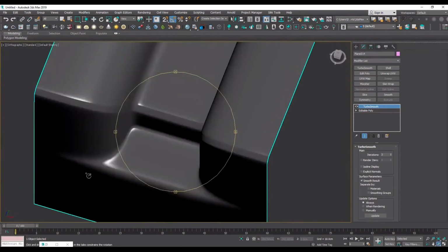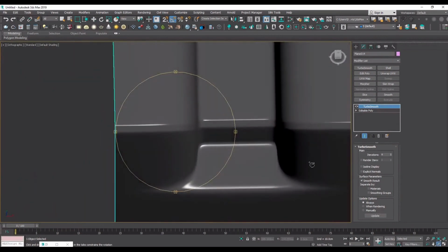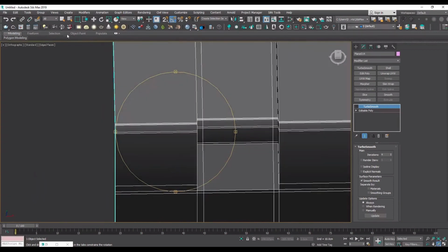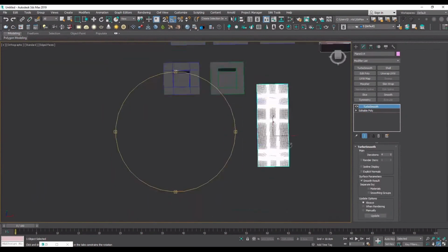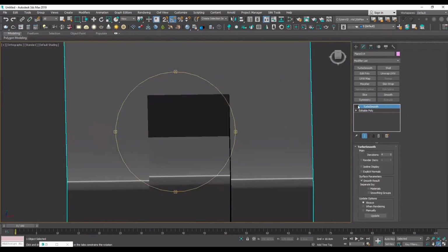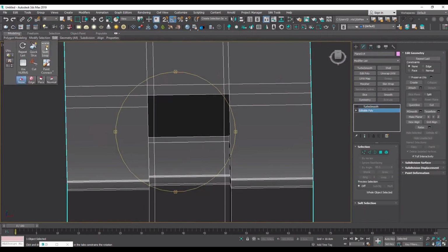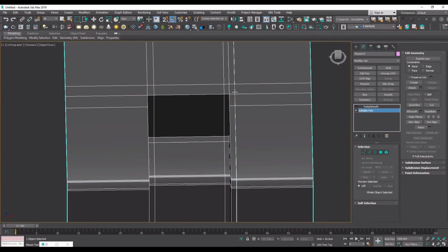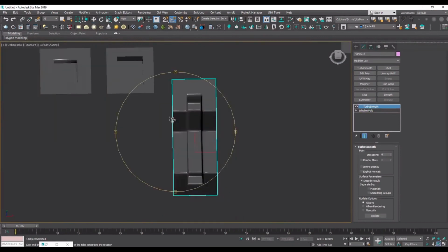But now we have to do this process on the outer parts to prevent a shading effect that we're getting because our topology needs something. The thing I did was to limit the edges to preserve the shape from Turbo Smooth. And that's what we're going to do for these two parts again. But this time our purpose is to eliminate the bad shading effects on the model.